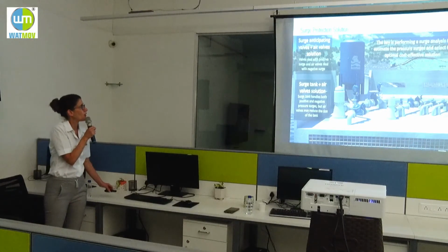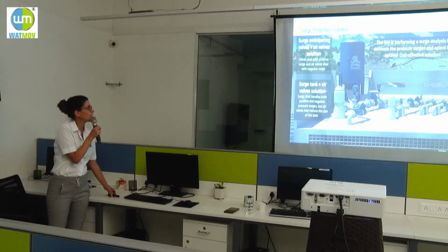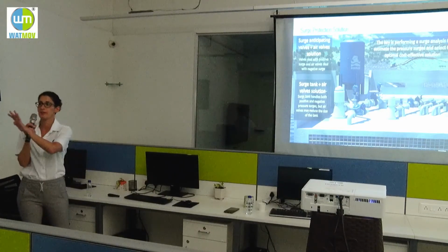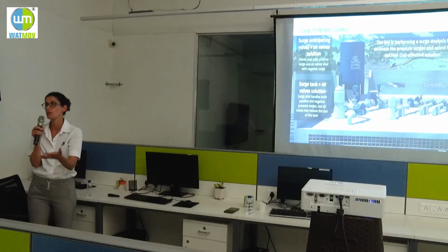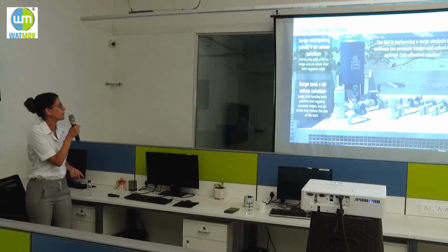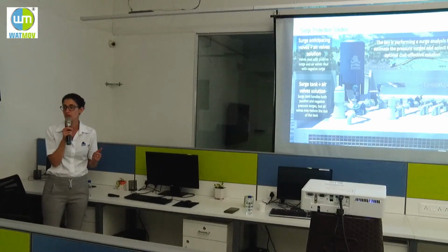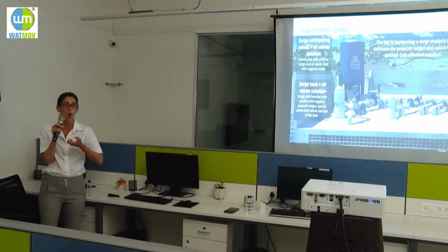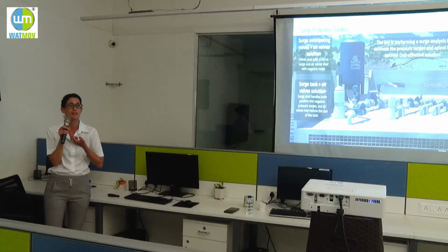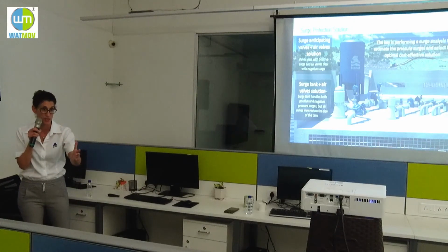So let's look at the Bermad solution and the traditional solution that is very common in India, which is the surge vessels. Unlike the surge anticipating valve, the surge vessel absorbs the energy. It does not dissipate the energy.